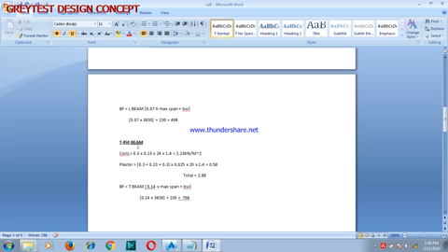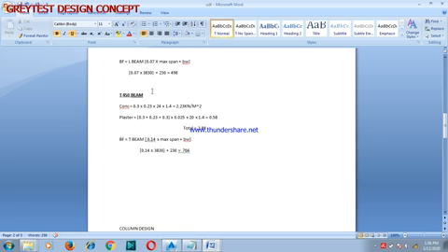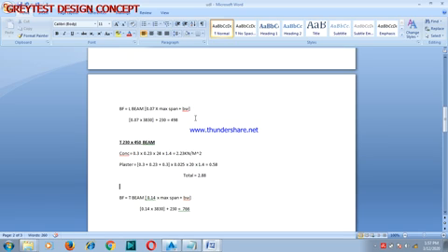Now when you come to your T-beam, the same thing, just like I explained for the L-beam. When you have a 230 by 450 beam, you always use the value 2.88. That means when it changes, definitely this value 2.88 will change. When you have a 230 by 600 beam, this value changes. But this is just a simple way to get whatever value you want to use here. It's just like the self weight of that particular beam.